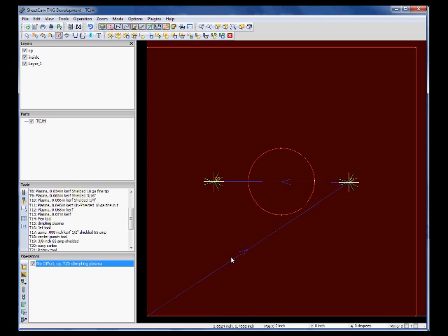Now, generally what you do is you have an additional hole punch that might be in here, because they say the first punch actually stays on a couple of milliseconds longer, and therefore it punches a little bit bigger. So a lot of times I'll either put it in something that's going to fall out later on, or I may put it outside of the usable part that I have. But anyway, you have one that is basically a sacrificial punch, and then the second two, or however many you need to do it, you just go and click with that.